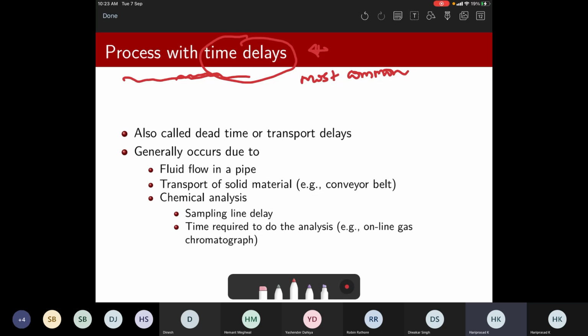because there are various interconnecting factors. The input that you have given. So what is your input here? The input is you pressing your accelerator, which essentially means that more fuel will be burned. But that requires, let's say, nozzles to be open, and the injector has to send more fuel into the cylinders and burn it. So that takes a couple of seconds. Of course, it is not minutes, but again, some seconds.